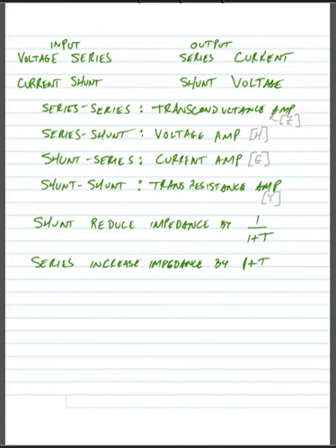All right, we can make a few further notes about the types of parameters that we use to solve these circuits. So we've already seen a few of these amplifiers. For our transconductance amplifier, for instance, we use Z parameters in our feedback network. For voltage amplifiers, we used H parameters. For current amplifiers, we will use G parameters. And for trans resistance amplifiers, we will use Y parameters. And we'll learn to use those in the next part of the lecture.